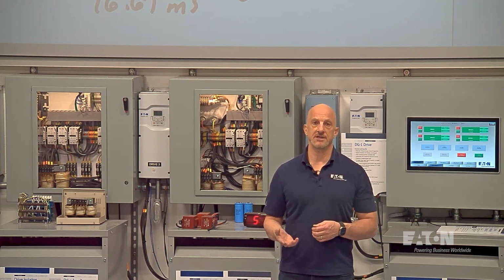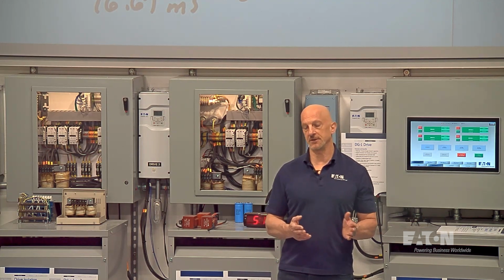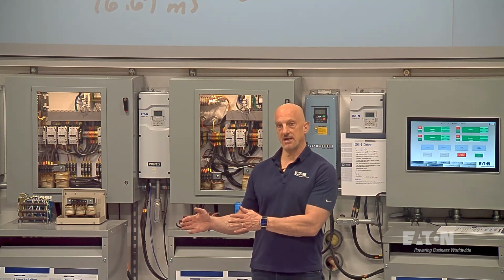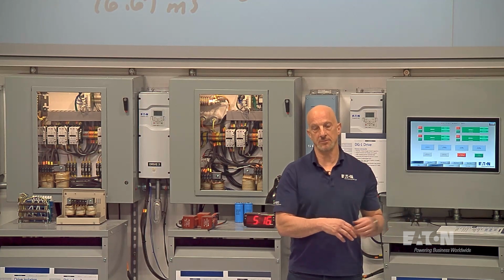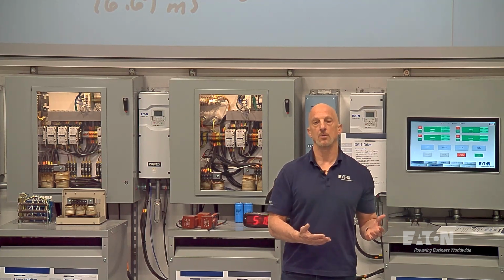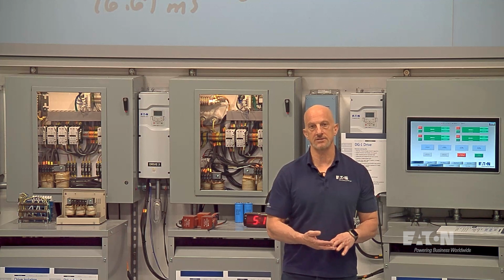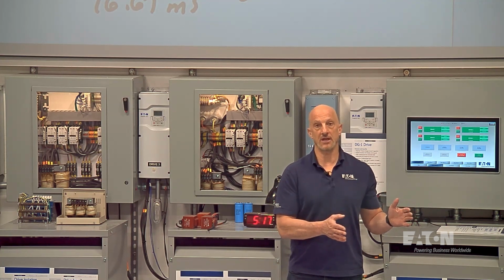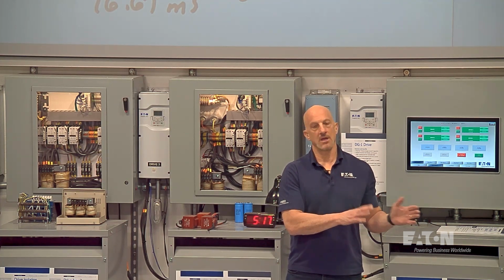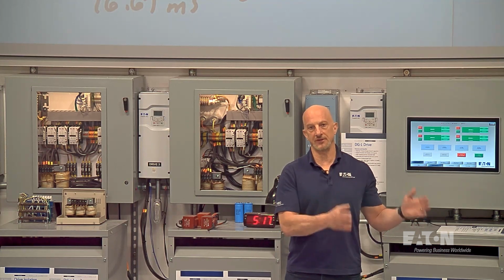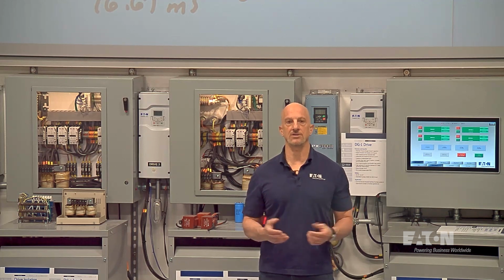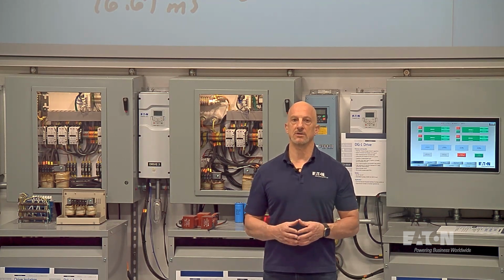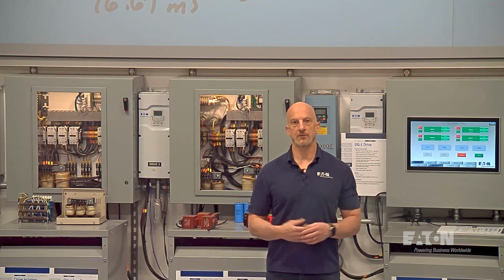One of the things that we've seen specifically is transfer switches, because it thinks a source on this side has 60 hertz and a source on the other side, with the notches and the multiple zero crossings when you're loaded with harmonics, like drives and other things, might have a frequency that looks much higher, 180 hertz. Well, of course, it's not 180 hertz, but it's 60 hertz voltage with multiple zero crossings and notches. And that's really the concern. Again, misoperation from voltage distortion.